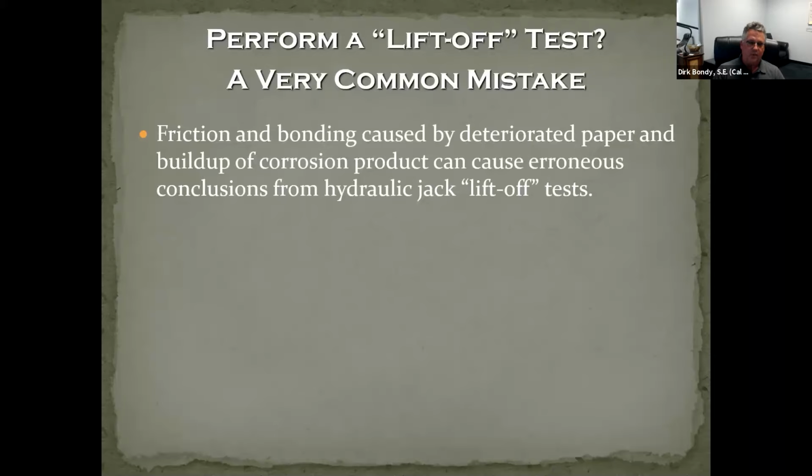The problem with this is if the tendon has corroded and it has failed, or it has no more pre-stress in it, that corrosion byproduct will still, it actually grows on the tendon. It will actually grow and bond to the concrete, even though it wasn't originally bonded. It will bond to the concrete, and then it creates a serious bond friction. So you apply a jack to that, you will actually get high jack forces.